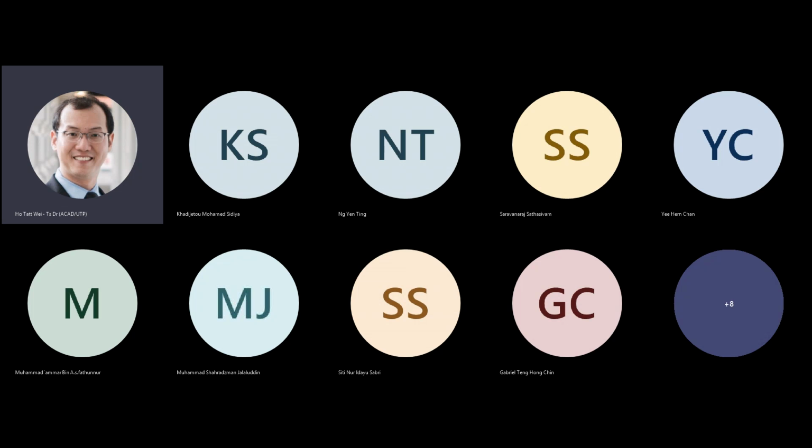Current I is rate of change of charge over time. It can either mean that your charge is flowing very quickly or you've got a lot of charge here. So guess what? Current I squared R, if there's a resistance, this generates heat. So if there is a high surge in current here, there's high local heat, the temperature at this junction elevates, and the device can also go into that mode where it fails to become a MOSFET.